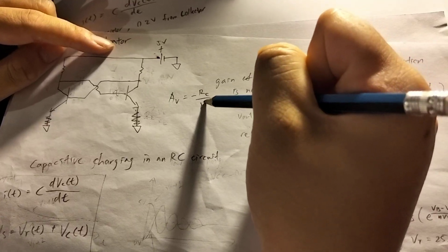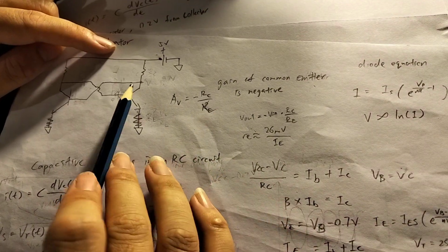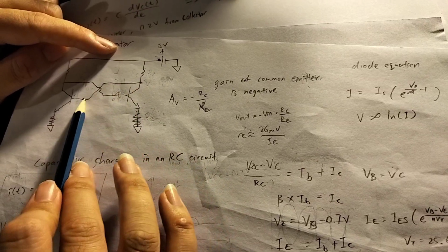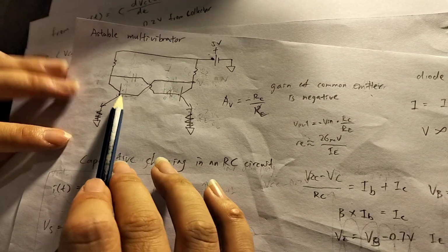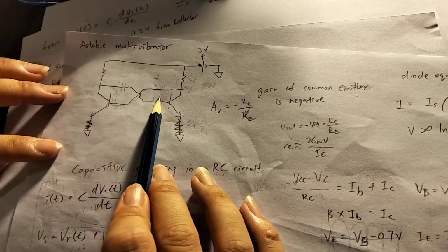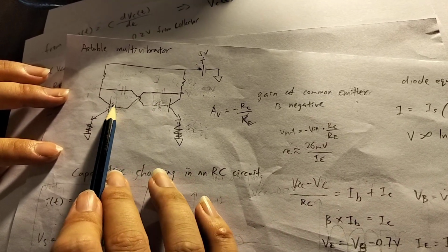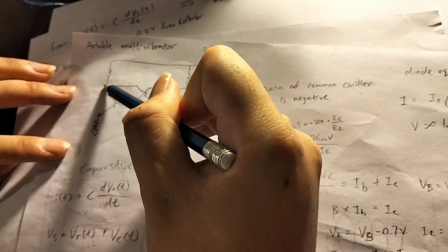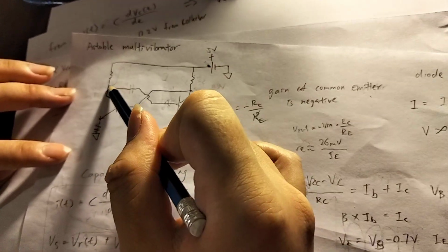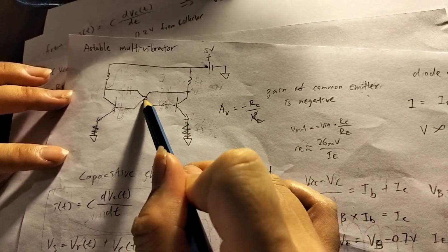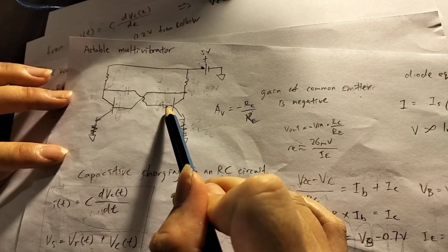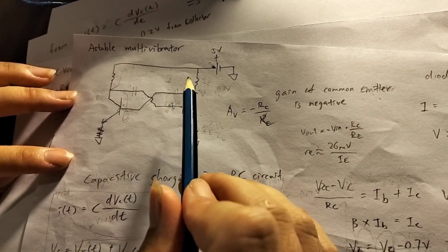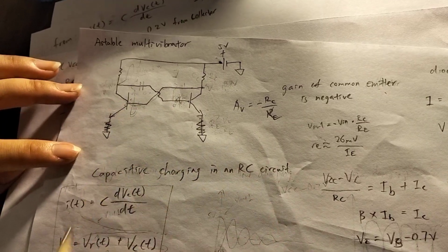This gain gets transmitted along the collector output to the other transistor. So when this transistor goes up a little bit, this transistor goes down a lot. And when it goes down a lot, the opposite effect happens here and it pushes this collector up a lot. Then it feeds back into this transistor, and it has a runaway effect where tipping one over will increase the other one.